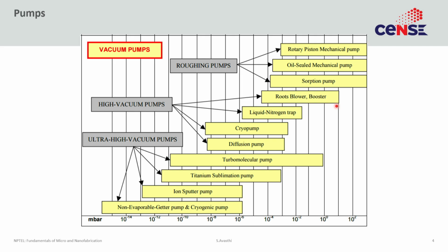In order to get better vacuum, you tend to need different techniques. The common ones are, for example, the cryo pump and the diffusion pump, but these pumps cannot function at higher pressures. So instead of having one pump, you have a series of two pumps. At higher pressures, you use the first pump to get it down to a certain low value, and once it is at that low value, you engage the second pump to push it even further.